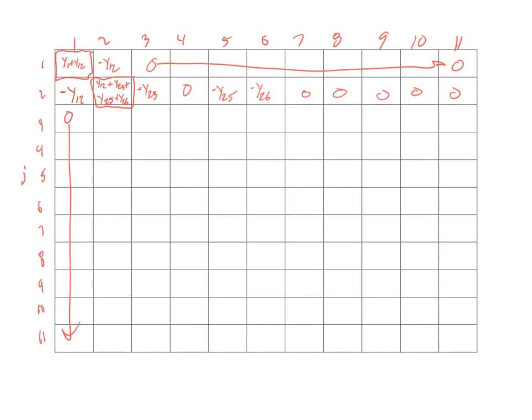If it's a self-admittance just connected to the bus, then I don't subtract it from any of the buses. So I can see that I have a y23, which means I have a y23 here. So there's a check, a y25 check, and a y26 check, and there's no other elements, so I'm good to go. So again, I have a symmetrical matrix, so this is minus y23, 0, minus y25, minus y26, and the remainders are all zeros. Now I'm on to the y33.